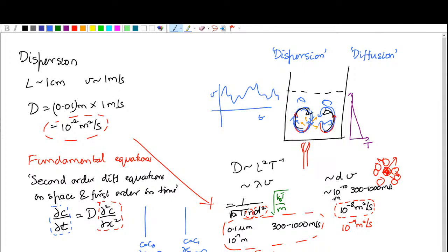For heat, depending upon whether the CSTR wall is heated or not, you either apply a constant temperature boundary condition if the wall is maintained at a constant temperature, or if you're doing electrical heating where you're giving it some pre-specified flux of energy, then you specify the flux of energy at the walls.